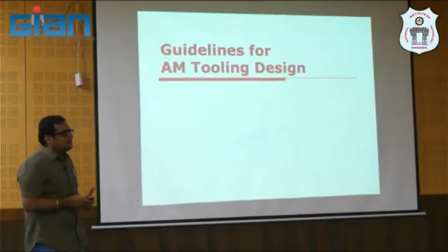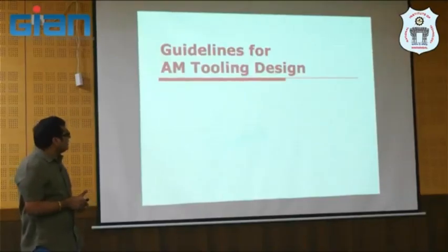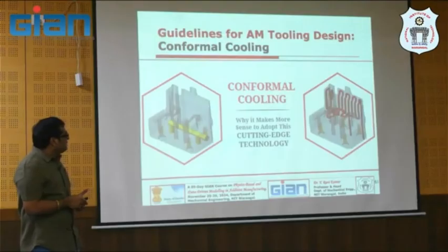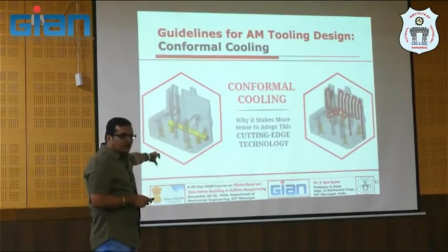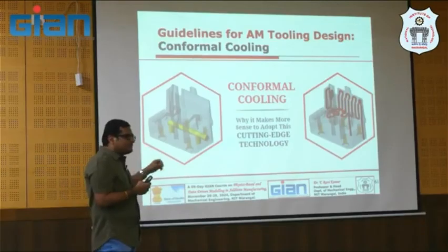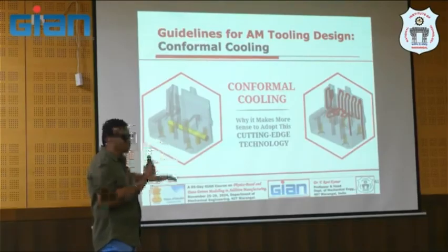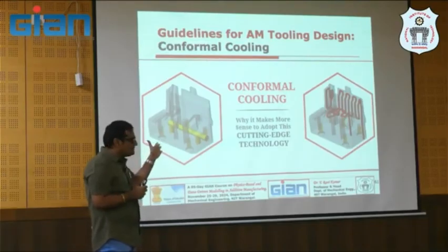Yeah, and then coming to the tooling, the conformal cooling channel, that's what we are talking about. Say you have a traditional tool, made by traditional manufacturing methods like drilling or any subtractive process. You can drill only a straight channel, right?